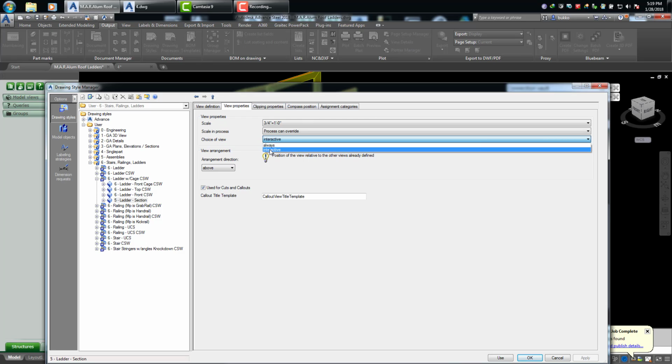And depending on the size of the run, if you're running a process, or if you're running a suite, if you want this to be automated, it's going to select the cuts that are basically parts that are welded to the main part. And so if you have a small spacing for your cuts, it's going to select a bunch of different cuts, and you're going to wind up with a bunch of cuts automatically on your drawings. If you're going to run a process, you're going to probably want to have those automated so that you can just go back into the drawing when you're scrubbing it and delete those cuts and only save the ones you want.